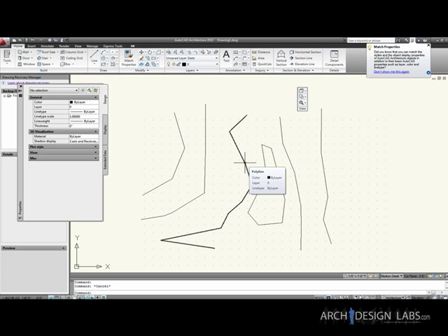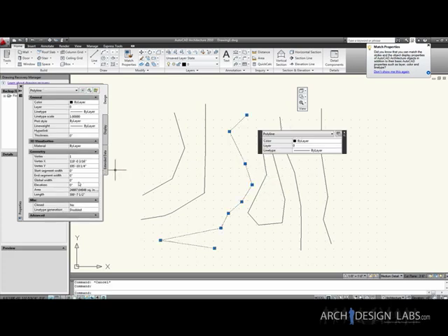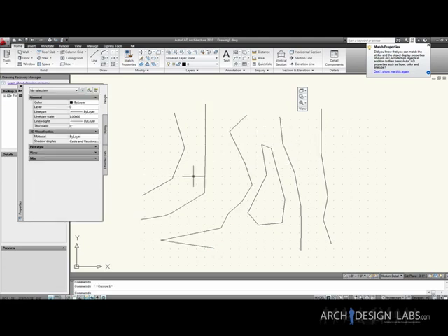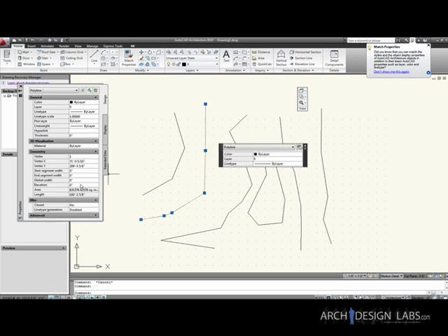But if you don't, then you need to come here and actually adjust the elevation. If you know this one's at 10 feet, you need to tell it to be 10 feet in the CAD drawing before you even import it into Revit. So that one's going to say 10 feet. I'm just doing this all generically. Sorry, I have to choose one at a time. Make this one 5 feet.